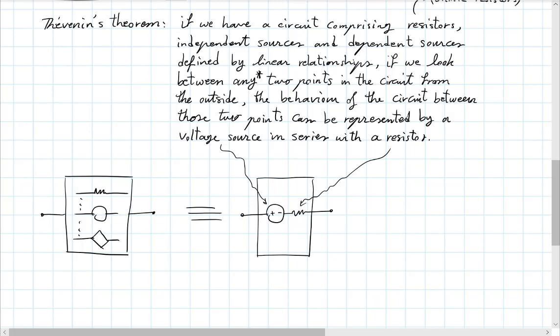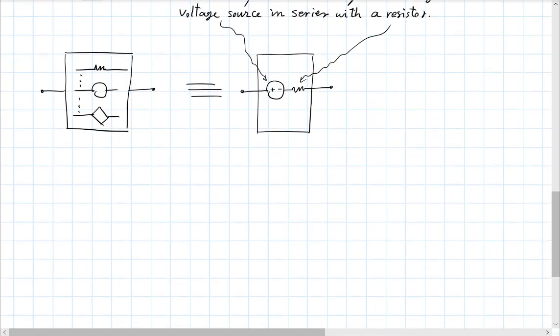So something like this. I think we wrote something like this last time. V sub j being A1j source 1 plus A2j source 2, and so on, up to Anj source n. So if you have n independent sources, any voltage or current in the circuit would be a linear combination of those.